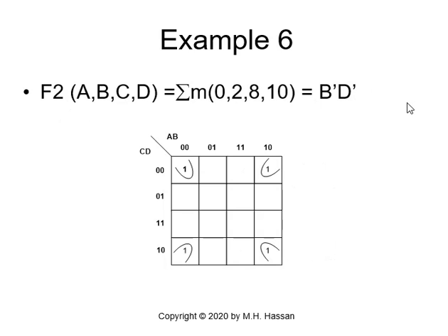Let's look at the next example. F2 will give me 1, 1, 1, 1. Here, we can imagine that this corner could be added to this corner, and this corner can be wrapped to this corner, so the shape will look like a flower. Those corners could be combined because all of them are logically adjacent. This will yield the following.